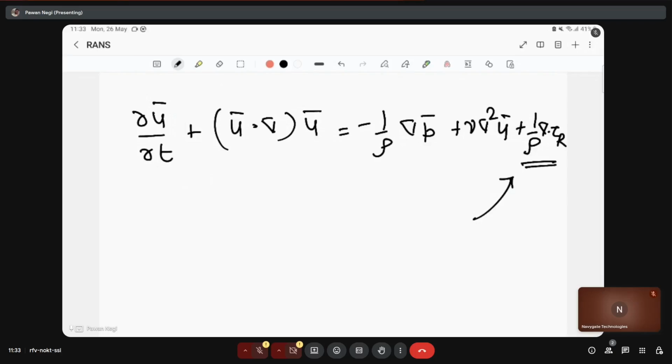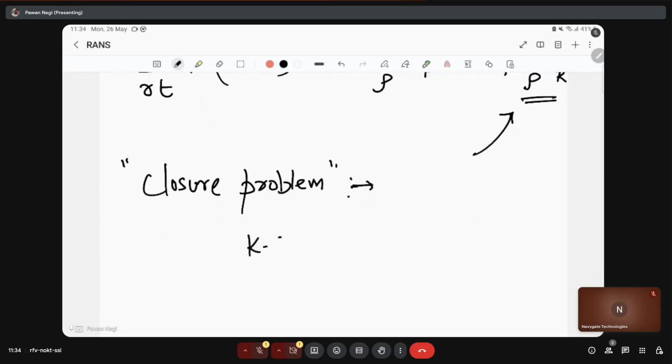clearly, on the derivation of the Reynolds averaged equation we get an extra term which is an unknown, the Reynolds stresses. So this leads to a closure problem, and to remedy this various models have been proposed. Some examples are the k epsilon model, k omega model, etc. As you have seen in the introduction of this particular course, we are going to go through these models and then learn how we can use these models in OpenFOAM and solve various problems. We'll also see how different models lead to different solutions and which model should be used in what kind of simulations. Thank you.